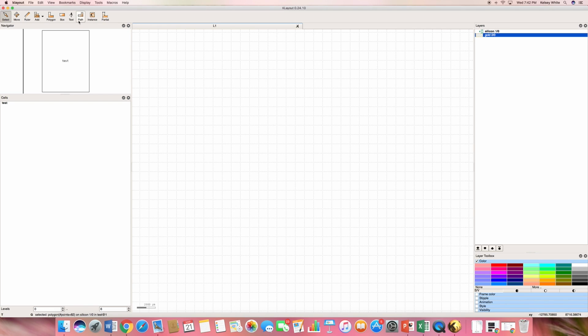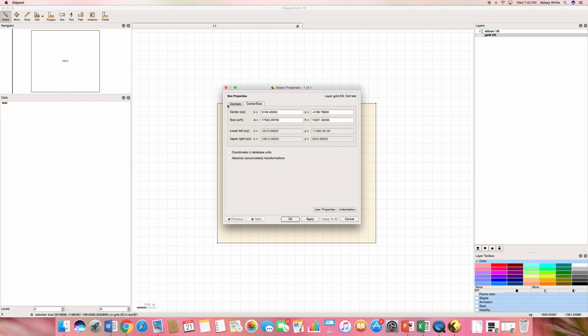And what I'd like to do is, let's say I wanted to make a wafer, just a template for a wafer. Well, I have this rectangle. A 4-inch wafer, I think, is something like 101 millimeters in diameter, which is something like 50.8 millimeters in radius. So let's do that. Let's center it first. It's always nice to center everything because then you know exactly where it is. And it's going to be 101,000 microns. And 101,000 microns there.